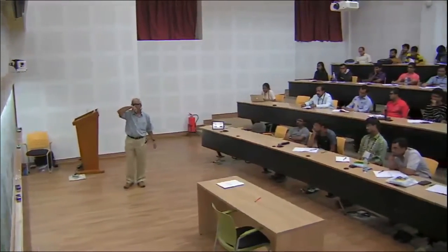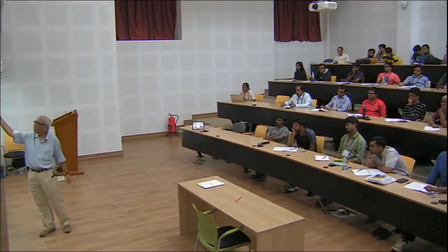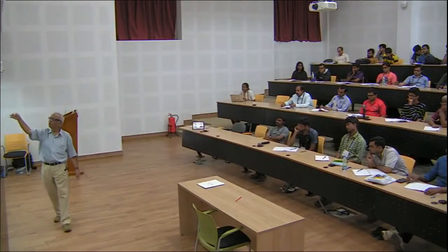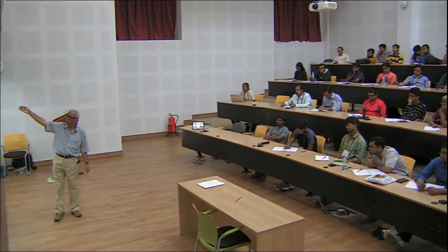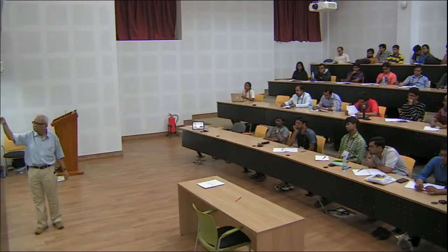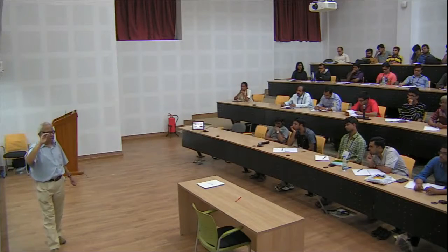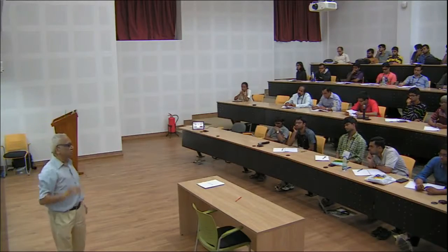And the obvious further development is that if you go up to Rayleigh numbers of the order of 10 to the power 10 and beyond, this 2/7 is no longer valid, it starts rising.